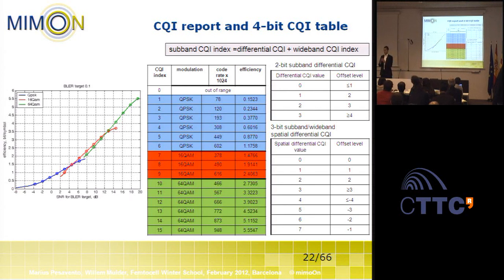This depends on the hardware, how good the hardware is, and on the algorithms that are implemented. Let's say if you have a MIMO detector based on zero forcing, then you will probably not be able to demodulate 64 QAM signals. If you have a sphere decoder, then maybe you can do it at a particular SNR. So it heavily depends on the implementation and the hardware.